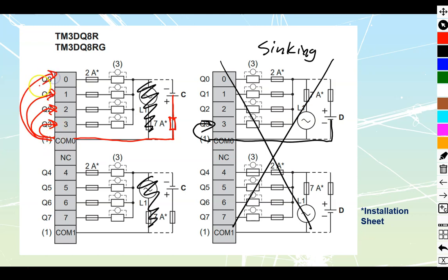What we see is that on the output, they also suggest that you have a fuse coming out of here. You're taking that positive out. They're suggesting a 2 amp fuse for those. They do suggest type T, which is a harder type of fuse and fuse holder to find. And then we take that positive through to my load itself, and then from my power supply, we wire a negative back to all the rest of my loads, the way that they're shown over here.